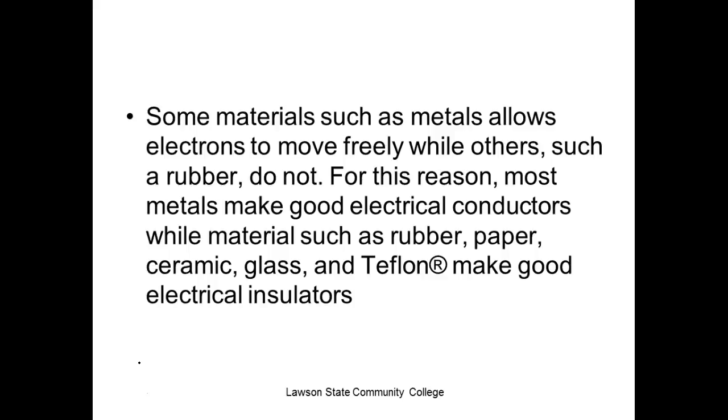So insulators are to contain the push. The thicker the insulator, or the material of the insulator, determines how much push that thing can take in there. What's the function of the wire? To carry the current, right? So conductors are rated in amps. Insulators are rated in volts. Okay, y'all understand the difference?